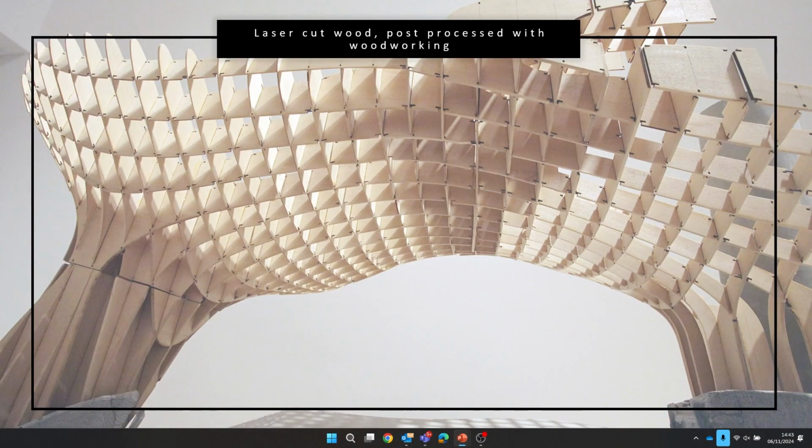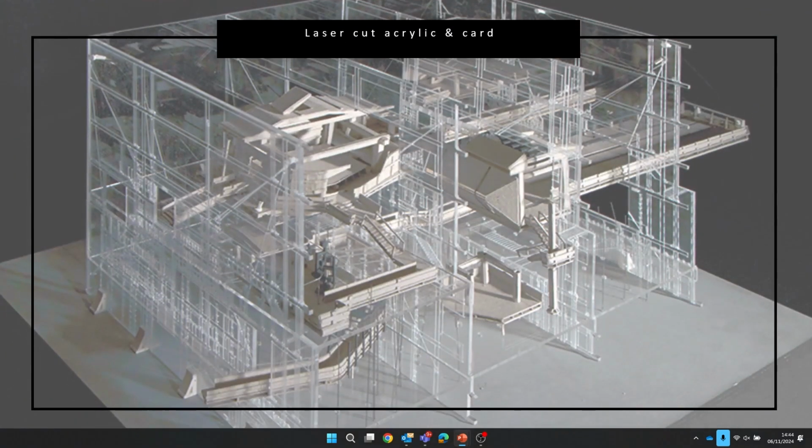This is the Metropole Parasol building I was talking about. You know when I was saying about the CNC with the little bunny ear cutouts? Imagine with an interlocking structure trying to chisel out all those corners on a scale model version of that. It would take you forever. So obviously if you're doing it on a scale model, you would just laser cut to get the sharp corners. But if you were making a CNC model, plunge cutting those corners would save you, what, a week of time, easily, of cutting stuff. So again, stuff to consider.